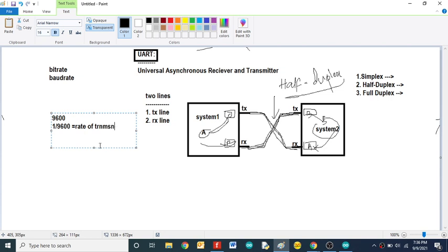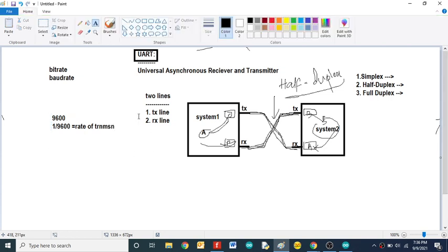Okay, so before you work with UART communication, we have to set the particular baud rate, the rate at which you are able to transmit data, or at which you are going to communicate between device 1 and the other device. Okay, so like that, the first thing we have to set is the rate for the serial communication. Okay, so after that, the internal working of your UART communication is,